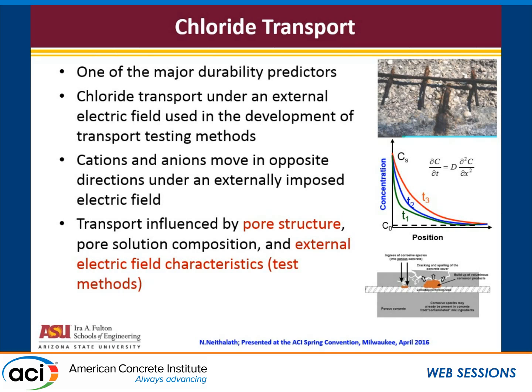So all specification purposes use a standard rapid chloride permeability test, which in fact is a pretty bad test for all practical purposes. It really doesn't measure what you want. It actually gives you a very happy number to play with. But there are a lot of confounding effects in the chloride RCPT test which need to be considered. But we will show a few different things.